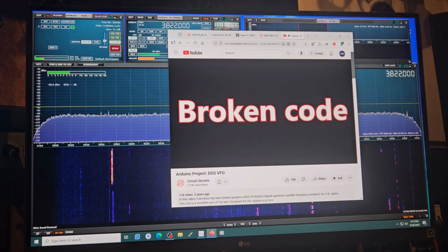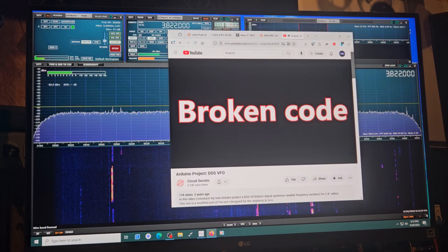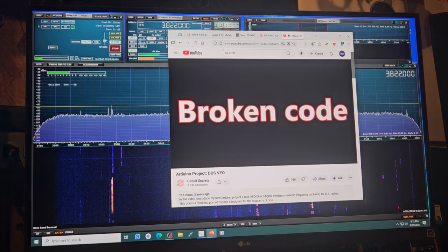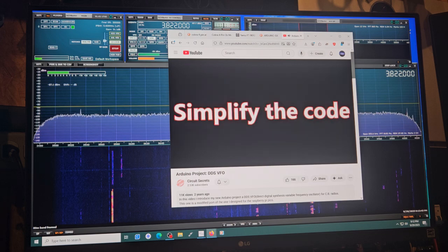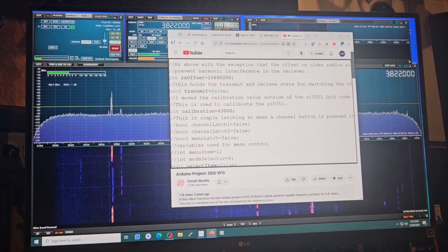The sketch and libraries seemed to be too much for the Arduino Pro Mini, and a conflict was occurring. I'm not sure what the exact conflict was, but all I'm certain of is that when the sketch would take more than 80% of available space, the program would not run. So I stripped the menu system and simplified the code so all the options need to be set in the source code before upload to the board.